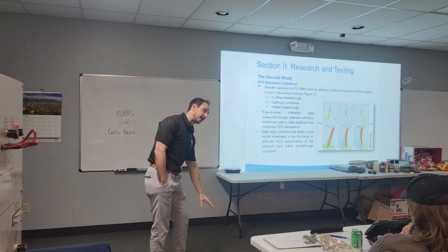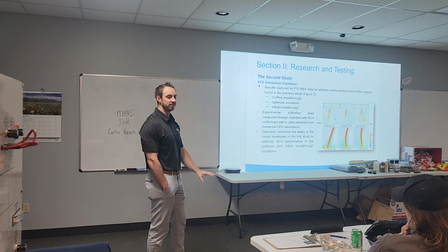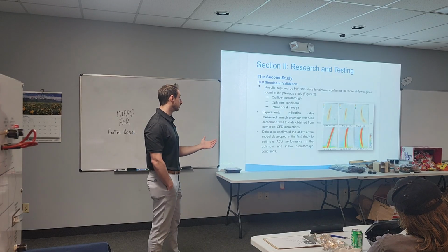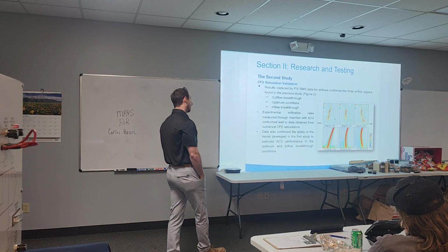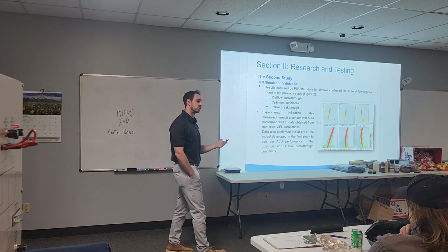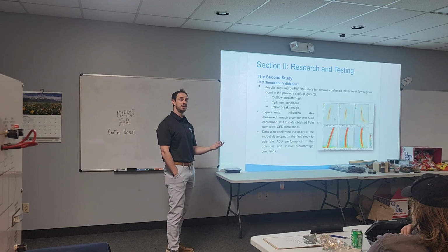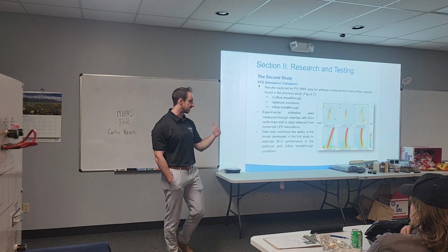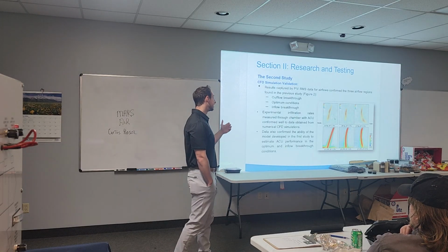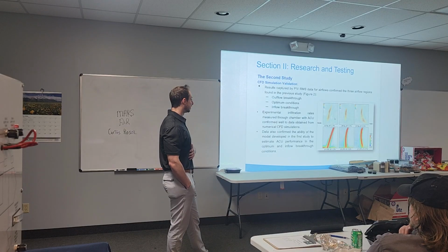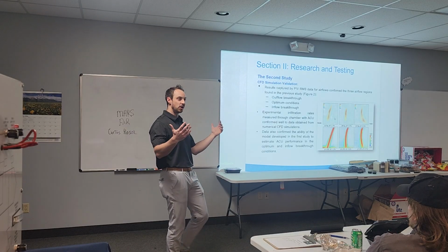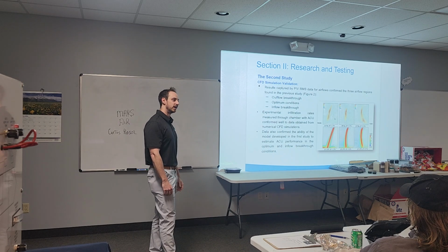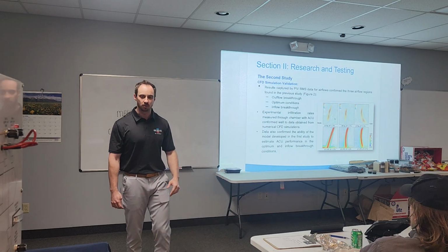So when they're complaining, hey, I'm getting no airflow at the bottom, what's going on? That's the first thing I would always recommend having them check, or if you're going in, having you check. And there's no solution, so I always like to preface with that, because you want to make sure the building's balanced before we put them in, to make sure we're able to actually get the functionality out of these. Unfortunately, if it's a $100,000 balancing issue, you can't fix it with a $1,000 air curtain. So I think that's the important thing to be aware of.